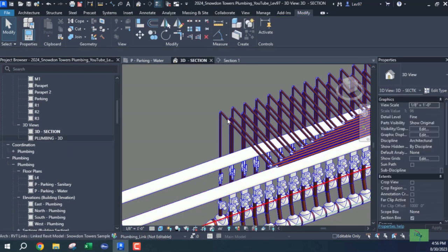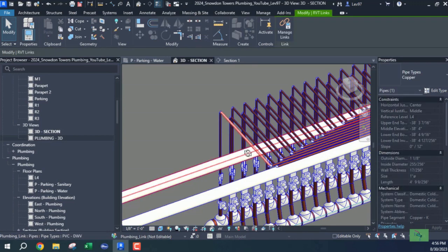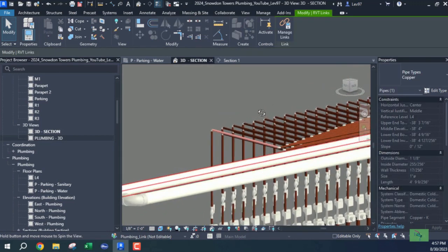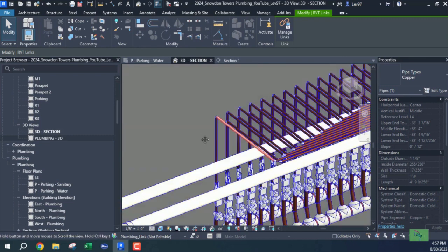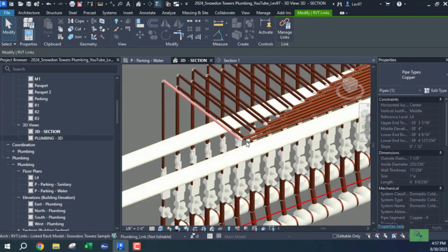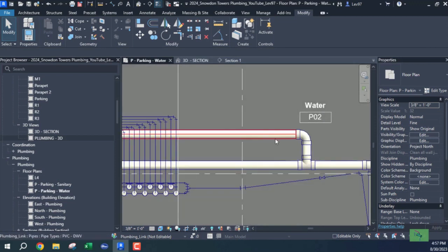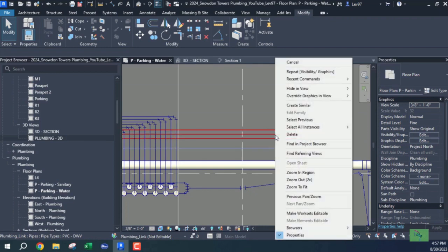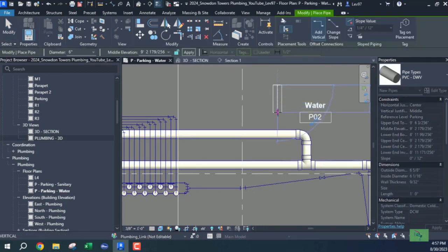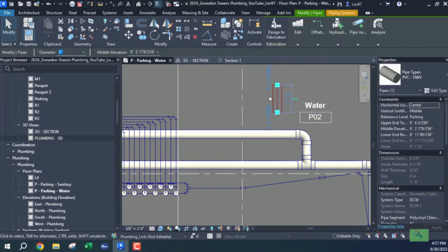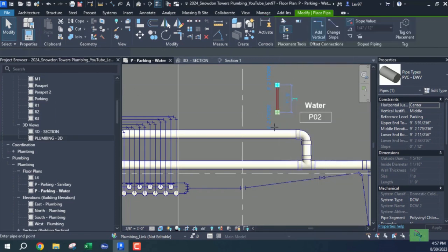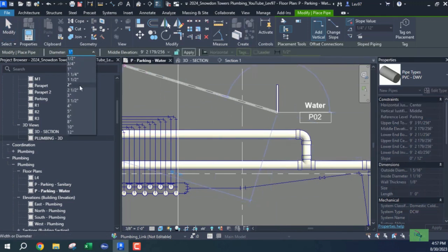Looking at that arrangement, where the pipe that I just clicked on is above, I'm going to try to duplicate that in some ways. What I'm going to do is choose this pipe and create a similar pipe, but in this case it's going to be a 1-inch, and I'm going to increase it to a 2-inch. So from here it's going to be a 1-inch, and from here, from a 1-inch to a 2-inch pipe.